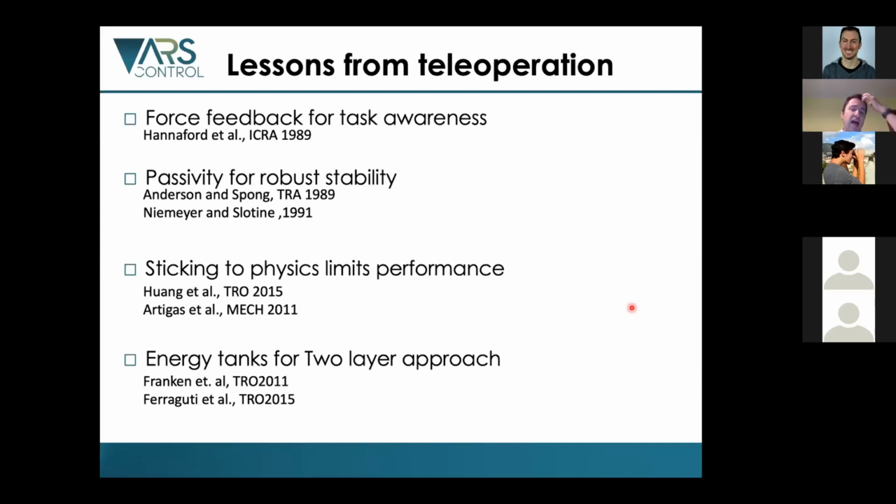So many works have been done to free passivity and allow the implementation of more flexible passivity-based controllers. Dongjun Lee proposed the PSPM, Jee-Hwan Ryu proposed the time domain passivity-based approach, and we proposed the energy tanks for the two-layer architecture in bilateral teleoperation.